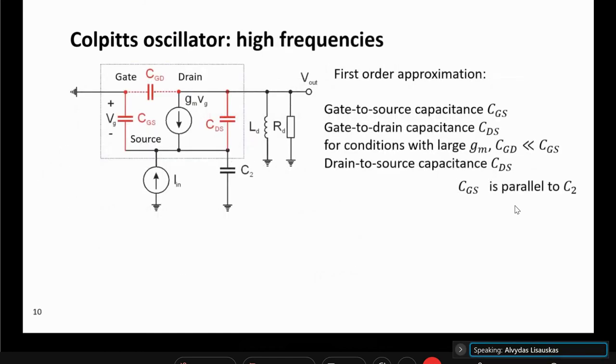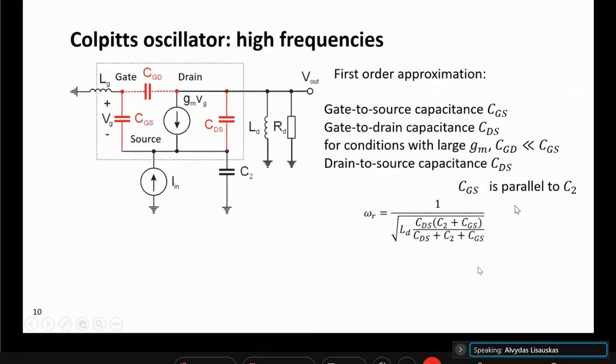But the point is, at high frequencies two additional capacitors come in here. The gate is shunted directly to source or to drain. And now if we take all those capacitances, and actually one capacitance is already inevitable, the drain to source capacitance belongs directly to the transistor, so it's also one parasitic, not directly considered. Now if we take those two capacitances, actually we would do the same analysis. That's also additional shunting here by a capacitor, but actually it's just capacitor action, nothing more.